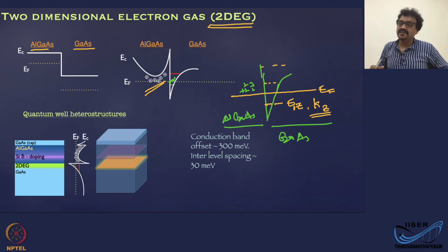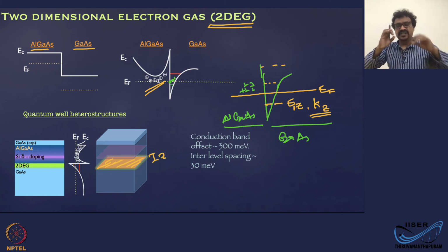What that means is, in that Z direction, the electron levels are completely quantized. There are no scattering events, okay. But the other direction is a sheet, just like shown here. The Z direction, which is vertical, is a thin sheet of electrons, where in the Z direction there is no motion possible. That means what you've got is a two-dimensional sheet of electrons, where the electrons are confined to move only in the sheet. The third direction, the Z direction, it cannot move.